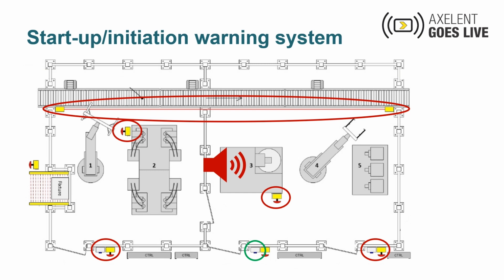The startup warning system is often also combined with so-called escape release switches on the doors. On these systems, the doors are often guard locked, so you can't get out normally. But with these special handles on the doors, they will open from the inside and an emergency stop command will normally be triggered that way.